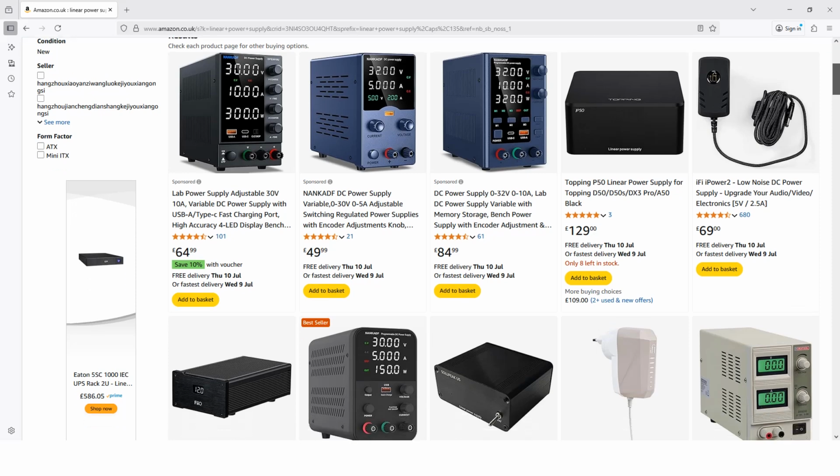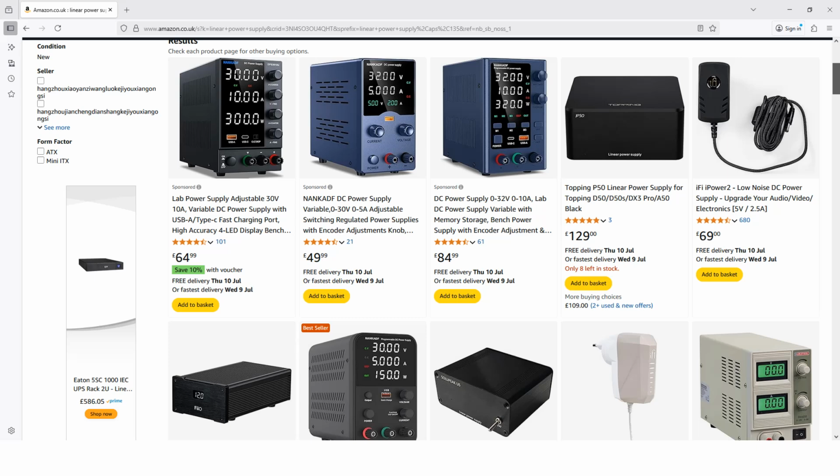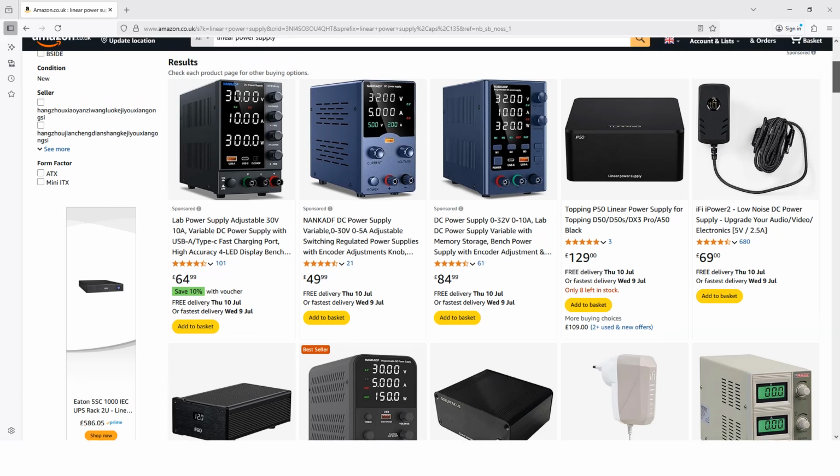If you put that on the scope, you see all kinds of noise. Usually it's lower frequency, because the switching is usually down in the hundreds of kilohertz range or something. But the harmonics from that can just be really nasty. All it has to do is go through some kind of a nonlinear device, a rectifier diode or something, and then boy, you can generate all kinds of harmonics that could go all the way up to whatever.